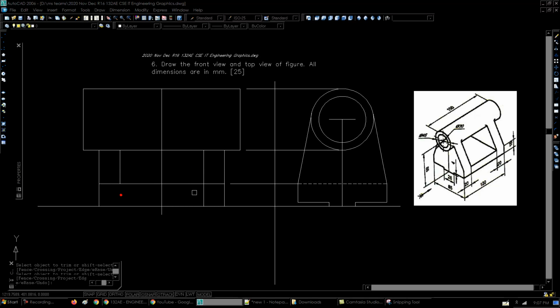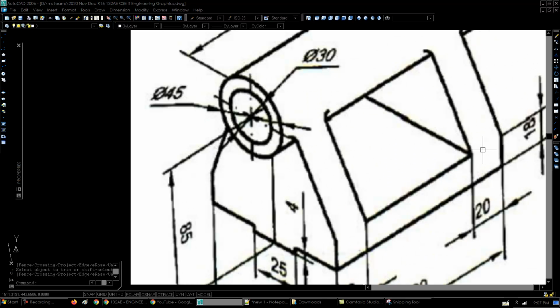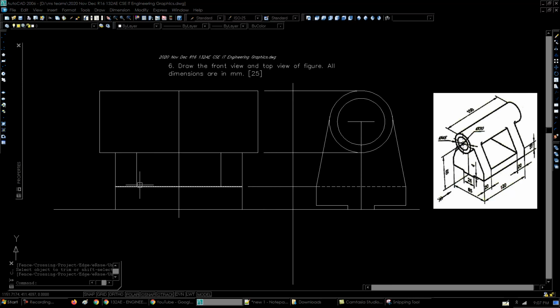This is not going to be visible, this is going to be whole, and of course, even though here you can see there is no edge given here properly, but there are two plane faces intersecting at this point, so this has got to be an edge. You can't just make it filleted. Even these edges, here the intersection has not been shown to be round exactly. It's a corner point, so because it's a corner point, there has to be a visible edge over here. So these parts, they have to be visible.